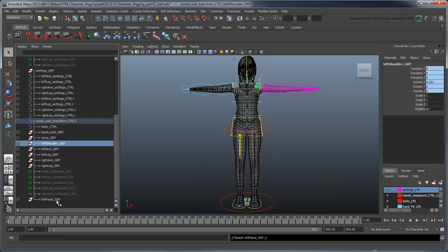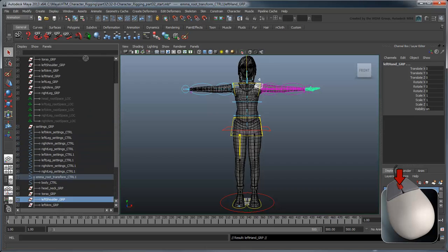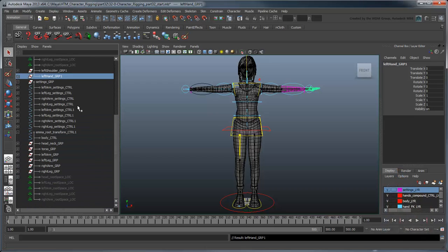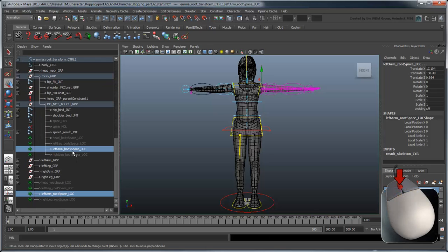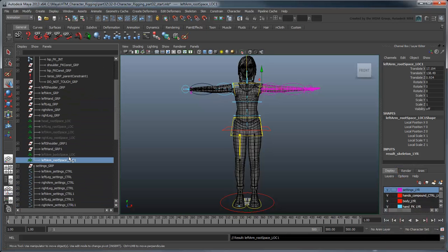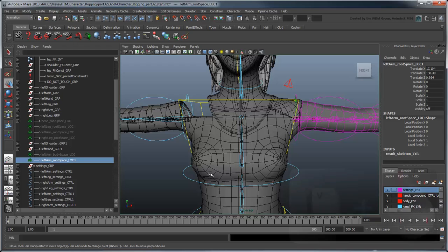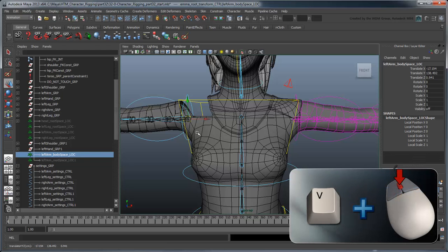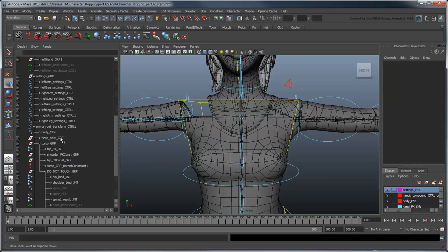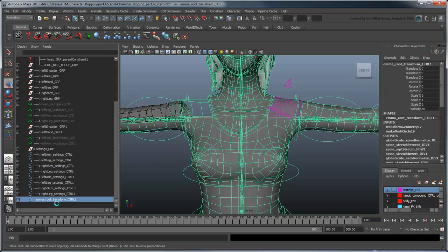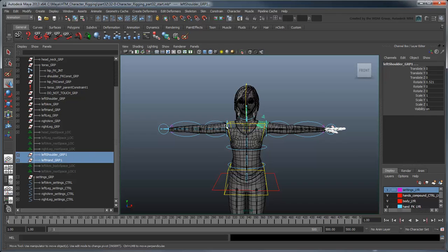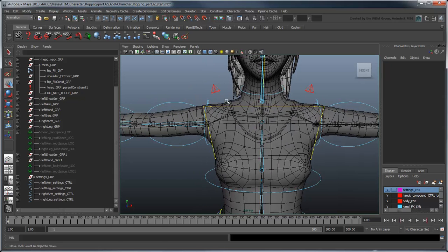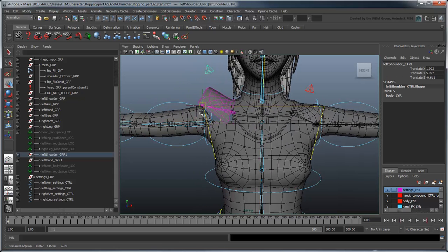Reparent the duplicated shoulder and hand groups to the EMMA root transform control. We'll also copy over the arm space locators, point snapping them to the right shoulder end result joint. Delete the rest of the duplicated rig. Now set Scale X on each of these groups to -1 to mirror them on the other side. Notice all individual controls are still intact and working.